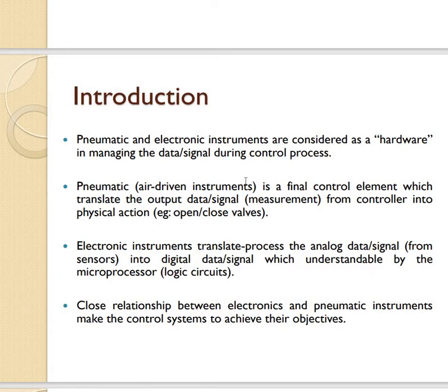So for the pneumatic, normally it is a final control element. So normally it is attached to the manipulated variable. It is used to translate the output data signal from the controller into physical action. So basically the controller will give the signal as an electrical signal.